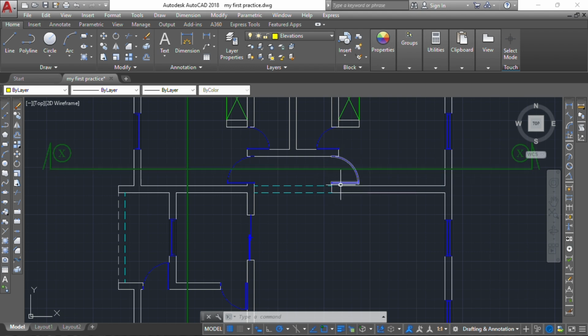Now, here that we have a door within a wall, there are two ways of doing it. The first one is we can show the wall and then indicate the door in between, and then we put in a lintel on top. The second way is removing the walls and putting only the door starting from the lintel level. Now, let's get this clear. Any wall we are cutting across, like these two walls here, and this wall here, which is not indicated there but indicated with a door, we'll be having a footing.